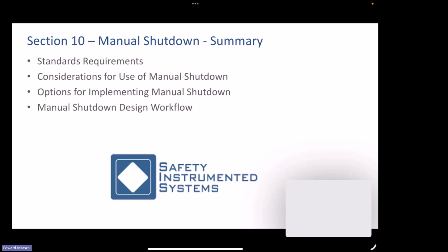If you go through the 61508 standard, you'll see that there are budgets. And there's usually a budget of 35% for your sensor, 15% for your logic solver, and 50% for your final element. So if your final element has a budget of 50% of 0.1, its probability of failure should probably be 0.05.